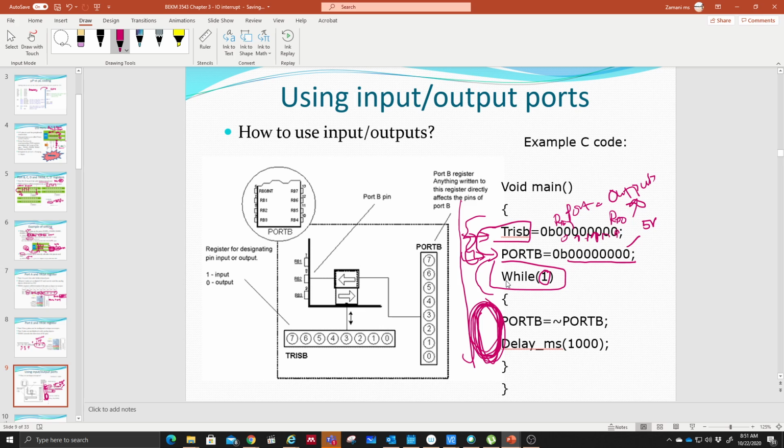So in this program, what it is actually telling us, you can see that the command will be port B is equivalent to invert. Invert means to invert back the port B. This is the invert value, this is the invert signal symbol. So it means that currently your port B, your pins are all actually 0 volt. All of them are 0 volt, right? When you say that the current one is going to be inverted, so the invert will be 0 going to 5.